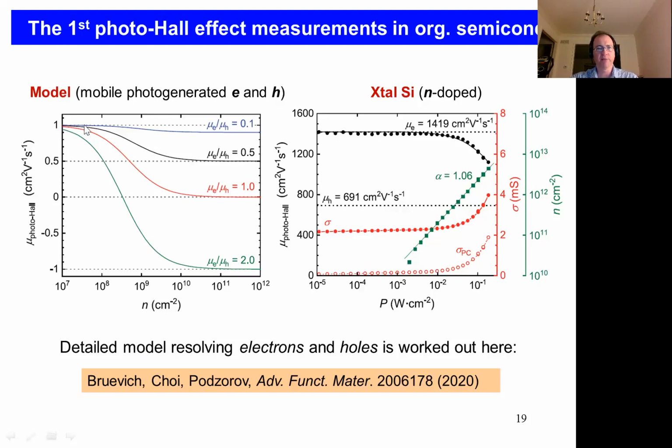initially you have some value, but then it rolls off and shows this kind of flattening, this saturation at high intensities. And the reason this happens is because in the low light condition, or in the dark, you may have some dark carriers, for instance, due to unintentional doping, probably holes, as in rubrene, or if the system is doped, it would be a certain type of carriers corresponding to doping.